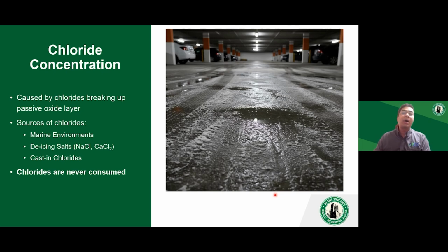In some cases, your parking garage or parking structure is really close to the sea coast. For instance, in Florida, we have a lot of parking garages that are very close to the beach, and that's where you would have chloride exposure because of the airborne chlorides. In some cases, you're dealing with parking garages that are underground, in contact with the nearby soils, and these soils can be really acidic, where the leachates from the soils can come into contact with the concrete and lower the pH of the concrete. And just the lowering of the pH of the concrete can result in corrosion of steel.